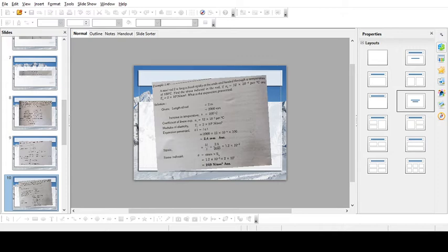Now stress induced is equal to strain into modulus of elasticity. So strain is simply 1.2 into 10 to the power of minus 3. Modulus of elasticity is 2 into 10 to the power of 5. So now the entire stress induced is 240 Newton per mm square. So this is the value you get.